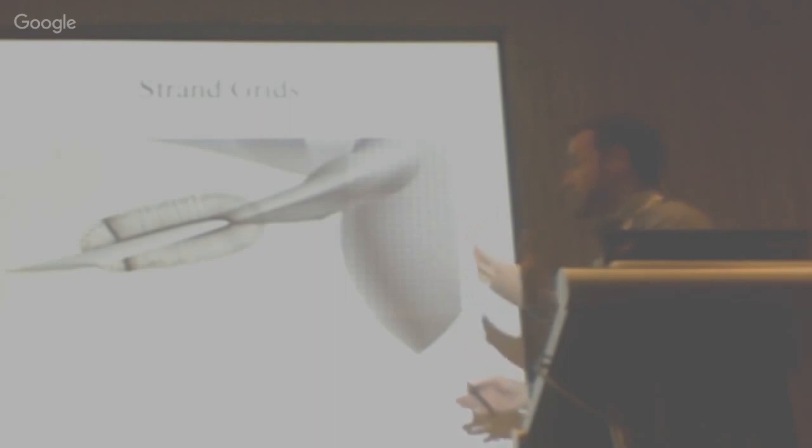And at the very edge of the strands, you can either put a farfield boundary condition if you're far enough away, or as in this case, you can mate with a Cartesian mesh. This is a great hybrid that works with using the Strand grids to resolve the near body features and the Cartesian grid to resolve the off body vortical features and things of that nature.